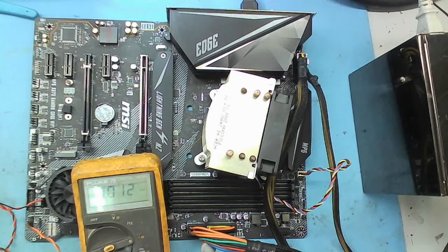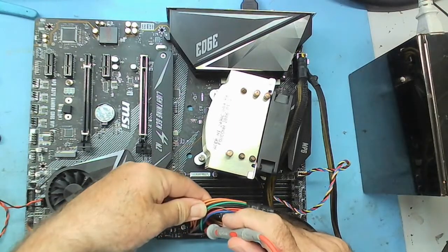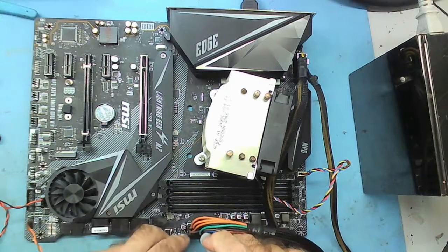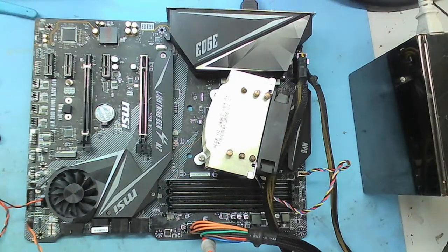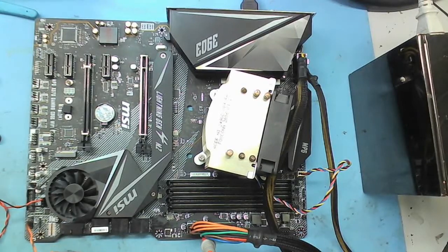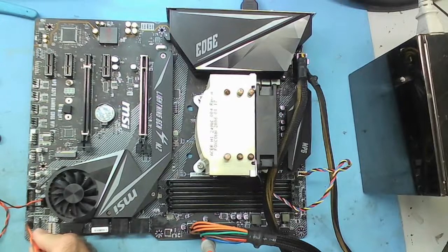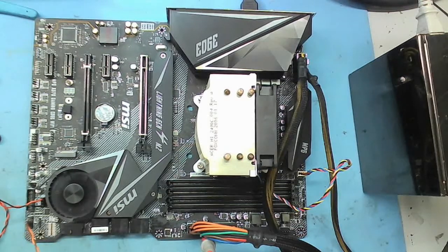So what we can do here, easiest way, is just take the meter probe off. I've still got the end of the meter probe stuck into the green wire, and I'm going to connect this to ground. That'll tell the power supply to switch on, and I want to see what happens. Does it switch on? It should do. Yeah. You see it now? Try that. The switch is on.